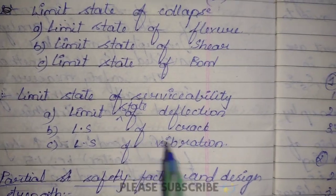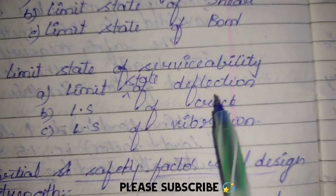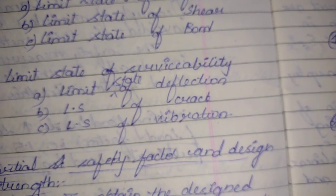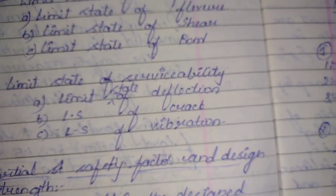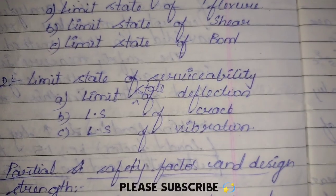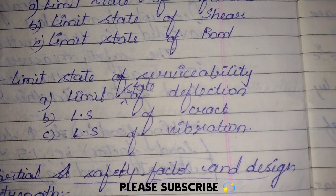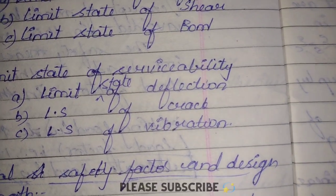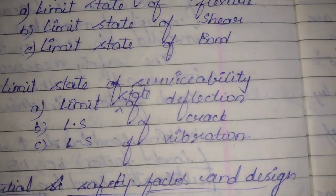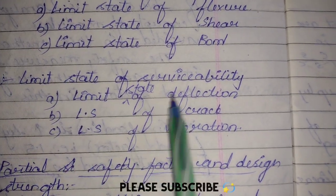Next we are having the limit state of serviceability. So as I've already explained you, it is the limit state at which the structure undergoes excessive deflection which affects the finishes, like causing some discomfort to the users, and excessive cracking which affects the appearance of the structure. Okay, whatever the aesthetic appearance or which do not affect the structure, like the structural performance is not affected by but the appearance of the structure is affected. Okay, excessive cracking or deflections or discomfort, whichever is coming, will be under this classification, the limit state of serviceability.